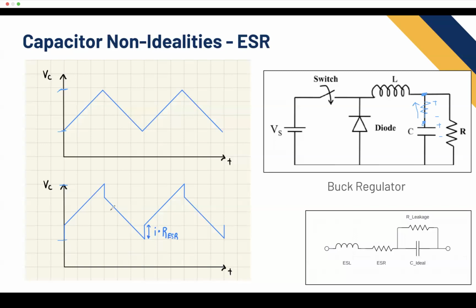But yeah, the reason this is important is because when you have your power rails, like let's say we're powering one of our sensors off of a buck regulator, you have to think about how noisy the power rail can be, and this is adding more noise to our power rail. So if something's ever losing power, or you think that something on the other side of the converter is pulling too much current, then this would be a good place to look. You would want to look at the switching waveform on the output of your regulator.